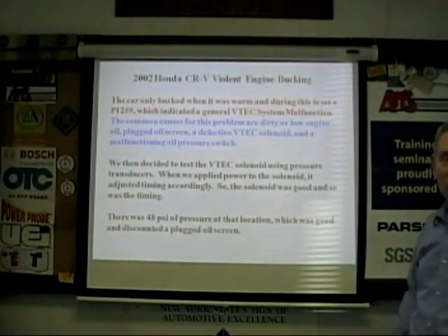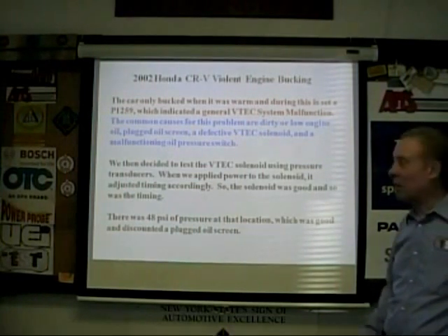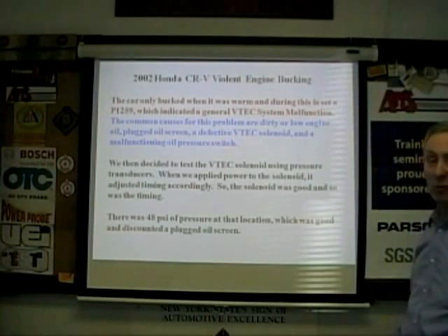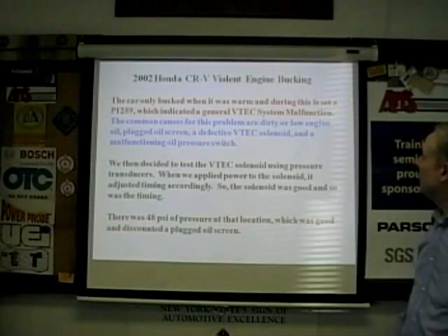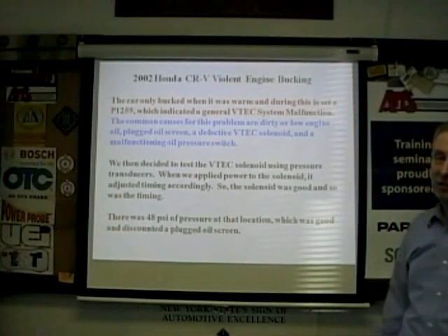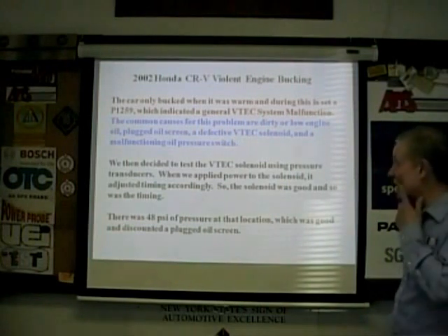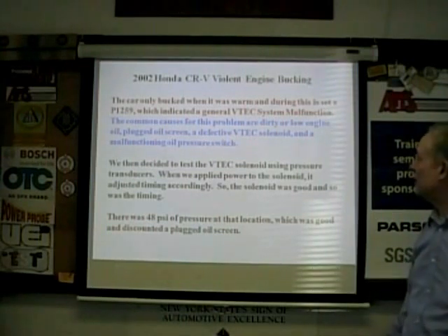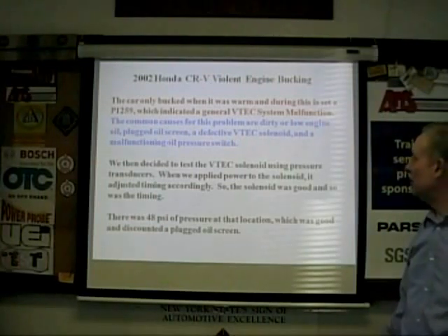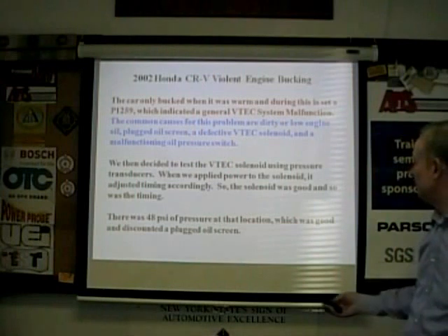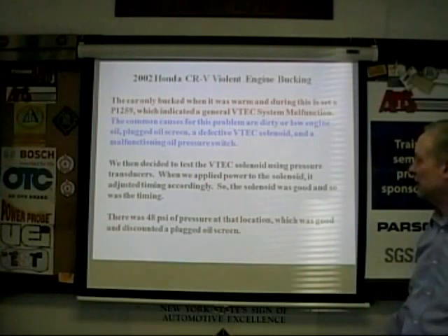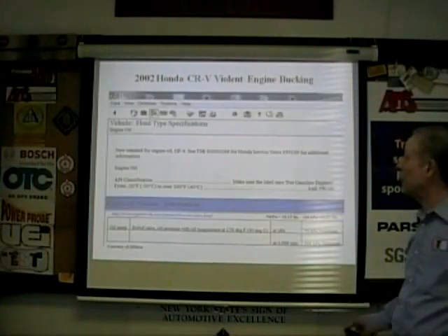So maybe if you tested that when it was cold, you would never see that. If it was cold, you probably wouldn't see any problem. It only bucked when it was warm, and when the oil was a little thinner. It indicated a general malfunction. Of course, you could change half the components in the system erroneously for this. Common causes, again, are listed here, and the shop decided to test the VTEC solenoid using pressure transducers. They applied power to the solenoid, and it adjusted timing correctly. They also measured pressure. It was 48 pounds at the location, which was good. They're discounting basically a plugged screen or a restriction.